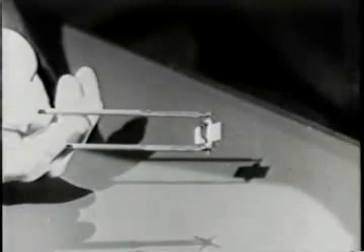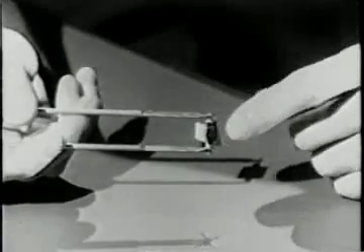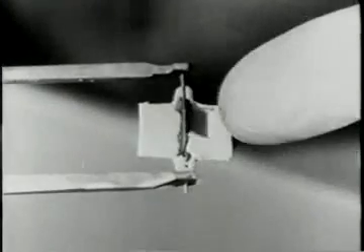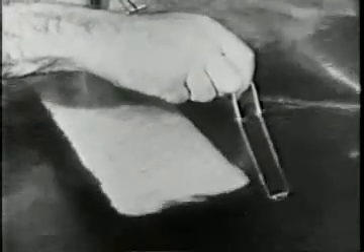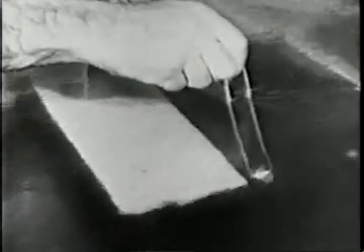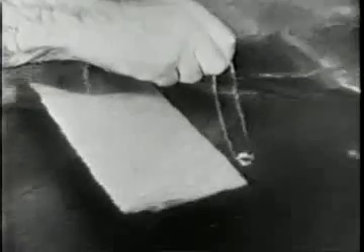This little vorticity meter shows streamwise vorticity if it is aligned with the flow. It is not a propeller because it turns only if the flow is spinning. If we put it behind a wing, right behind the tip it spins fast. Slightly inboard or outboard, it hardly turns. The trailing vortex is strongly concentrated at the wing tip.